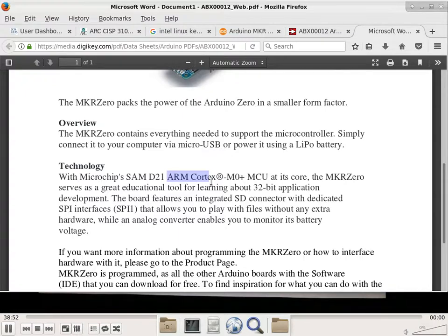Do you think your stack, below the stack pointer, can get corrupted? Well, not corrupted, but clobbered, overwritten. The idea is yes. Absolutely. So when you write code using these embedded controllers that has no operating system and is not running in protected mode, what we just talked about is 100% relevant. Is that making any sense?